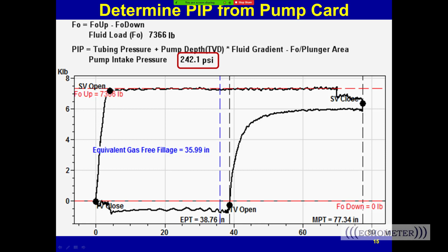That's a good question because this is software. Originally, when we first did the testing, 0.76 worked pretty well for a lot of wells in the Permian Basin, and I wasn't that worried about changing the viscosity. Then we started doing testing up in Wyoming, and we started seeing a bigger impact because we're starting to see lower API gravity crude. When we first programmed it, we didn't really know what to do because we didn't have enough experience with all kinds of crudes.